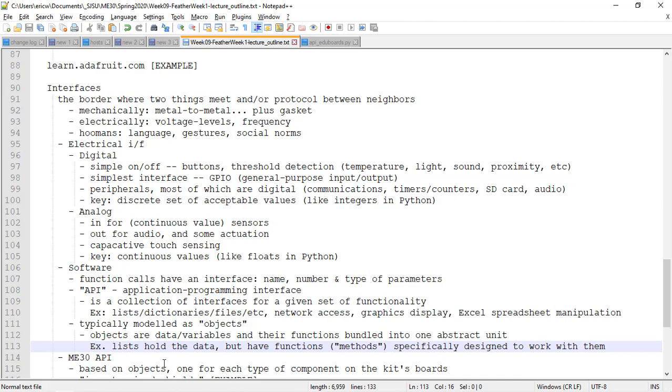An example of a mechanical interface would be when you put metal to metal, depending on what precision you're doing that with. Sometimes you need a gasket. So the interface could be metal to metal, or it could be metal to cork and then cork to metal again. But it's basically that in-between area where 2 pieces, like a valve head and engine block, meet to cooperate with each other, because one side needs to do something to the other, or communicate some sort of state or information to the other half.